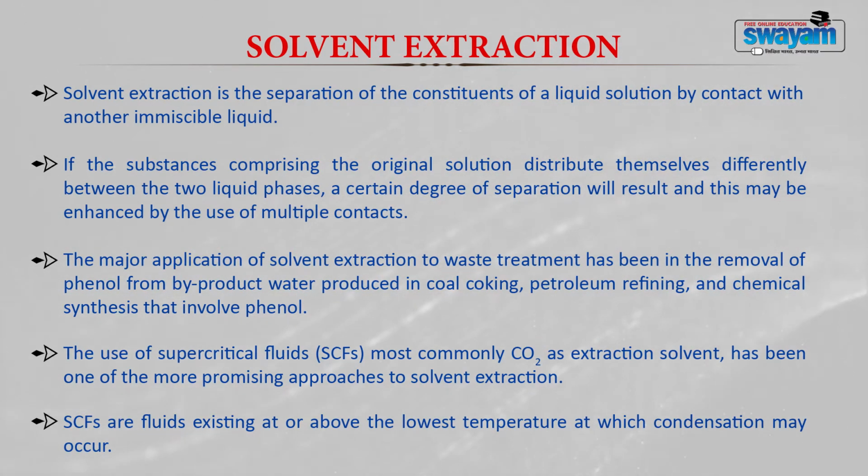Now, distillation. Distillation is again an expensive and energy intensive process and can probably be justified only when you want to recover certain valuable products like solvent recovery. Now, this technique has only limited application in the treatment of dilute aqueous hazardous waste.